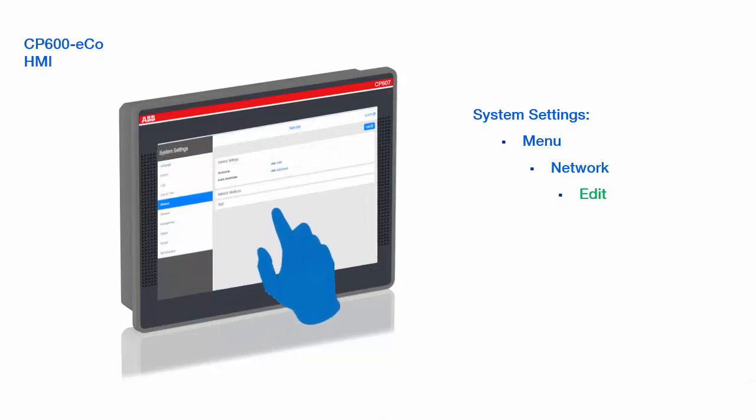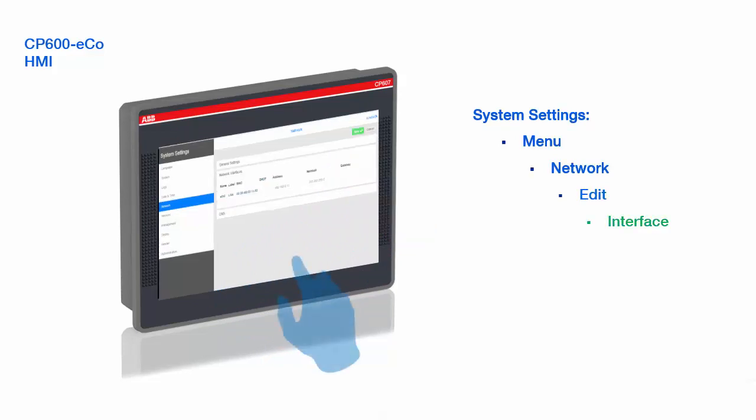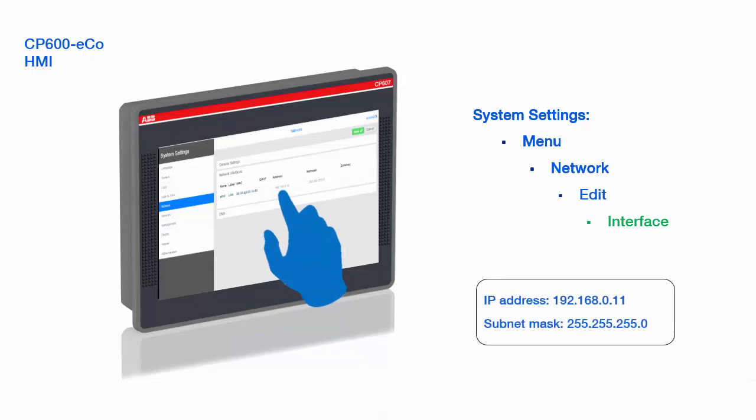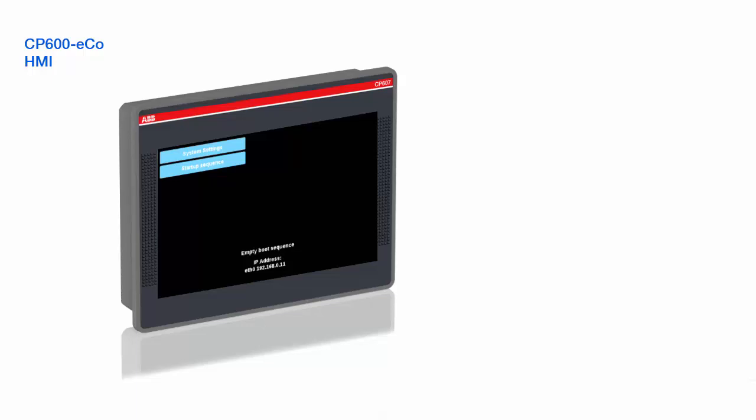We need to click on Edit on the page to be able to write and change the value of the IP address, according to the network used. Once done, click on Save to close and confirm your modification. The new values are active and could be used at once. The panel is now ready to install the runtime application from Panel Builder 600 Basic.